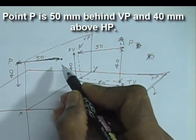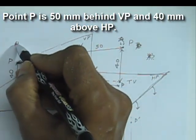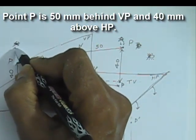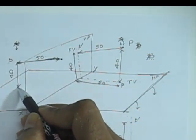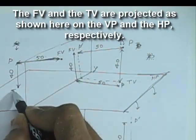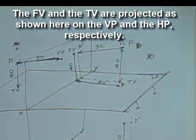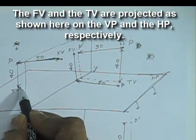So the observer is looking from the right side and the plane of projection is now in between the object and the observer for the front view. For the top view, the object is in between the observer and the plane of projection. So the front view and the top view can be shown.